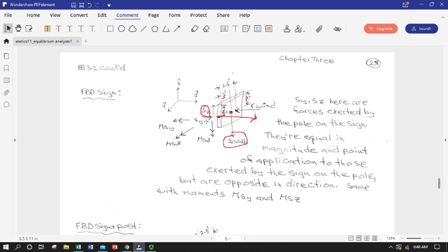So how do we depict that effectively with our reaction force? Well, here's a moment that we're saying that the post is going to have to exert in the J hat direction, and that's going to counteract that turning that the sign's own weight is exerting. In fact, you're going to find out there's a lot of moments. So S represents the force of the post on the sign, and MS is the moment exerted on the sign by the post.